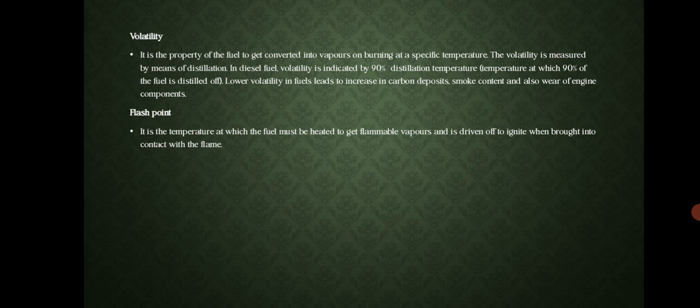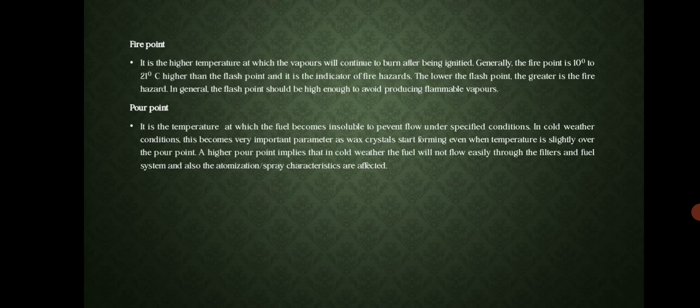Flash point. It is the temperature to which the fuel must be heated to give off flammable vapors that ignite when brought into contact with a flame. Fire point. It is the higher temperature at which the vapor will continue to burn after being ignited.